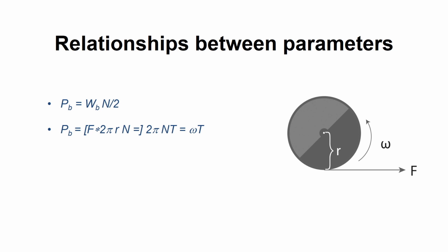can do it. Finally, another parameter is introduced called mean effective pressure, MEP, which is defined as work divided with swept volume. If the work considered is brake work, the mean effective pressure is called brake mean effective pressure, BMEP. In the slide, the relation giving the brake mean effective pressure is given, but as a function of torque instead of work. What one can see is that BMEP is proportional to torque, or load, and BMEP is often used to describe at what load an engine is operated.